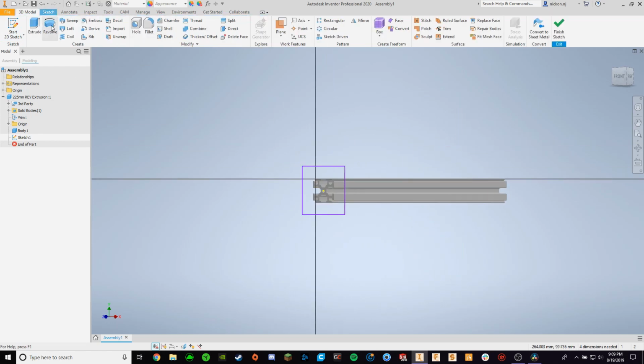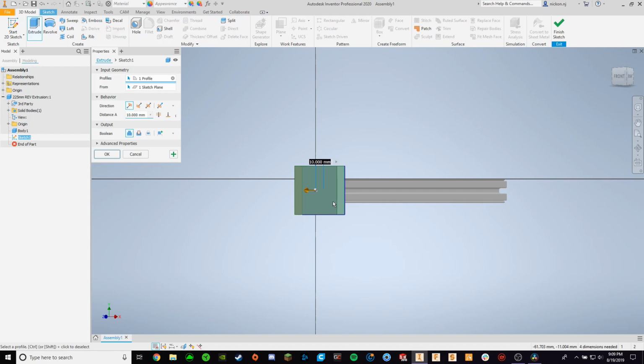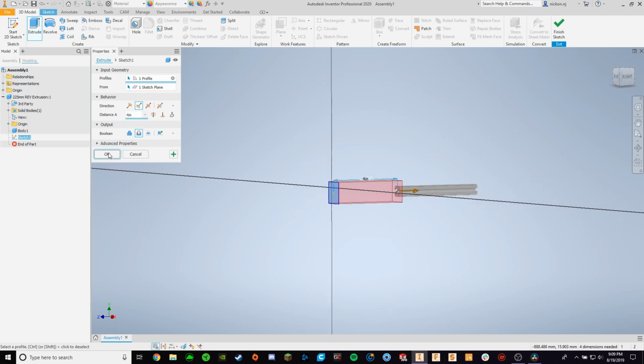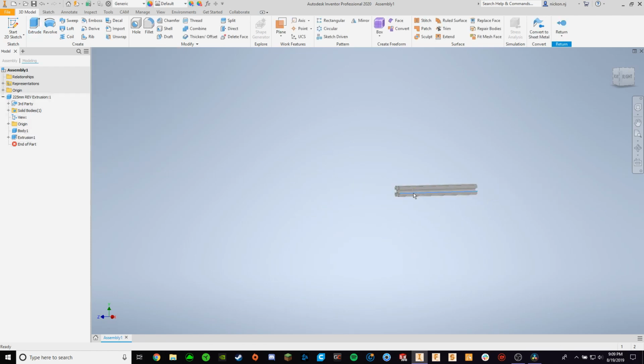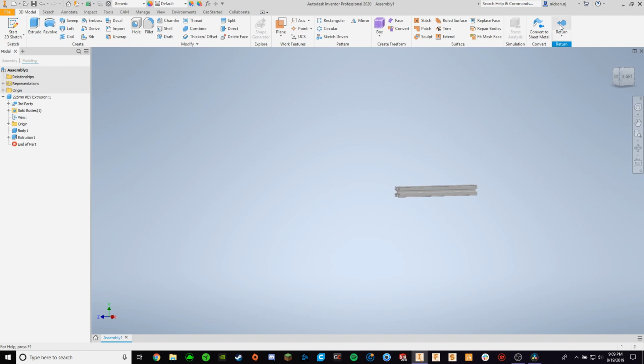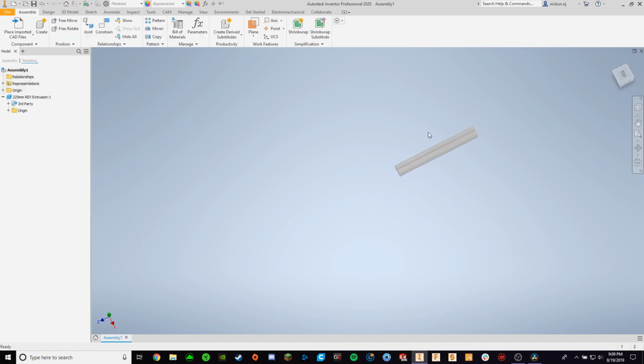And you can do this with any part in CAD, so don't be afraid to edit parts that you didn't make. Just be careful, as you might need to re-import a new version if you want to use that whole length extrusion again. So say I have this certain length of extrusion and I import that STEP file to an IPT. That IPT can only have one version. So if I have a 12-inch extrusion and I cut it down to 10 inches, if I try to re-import that same part, it's just going to come in as 10 inches again, because Inventor will save the edit that you made to the part.